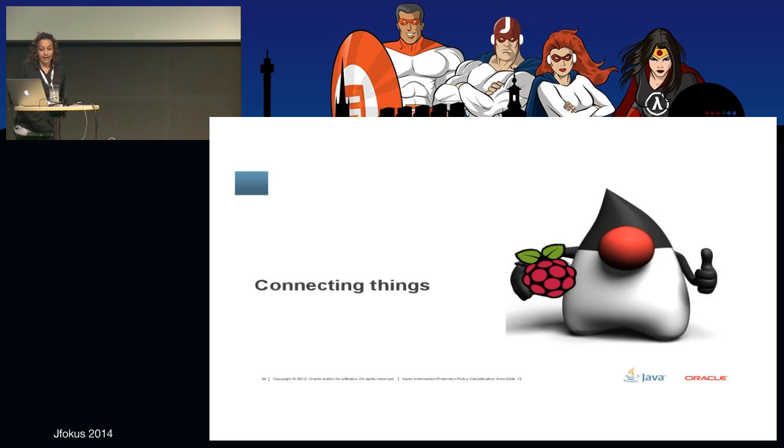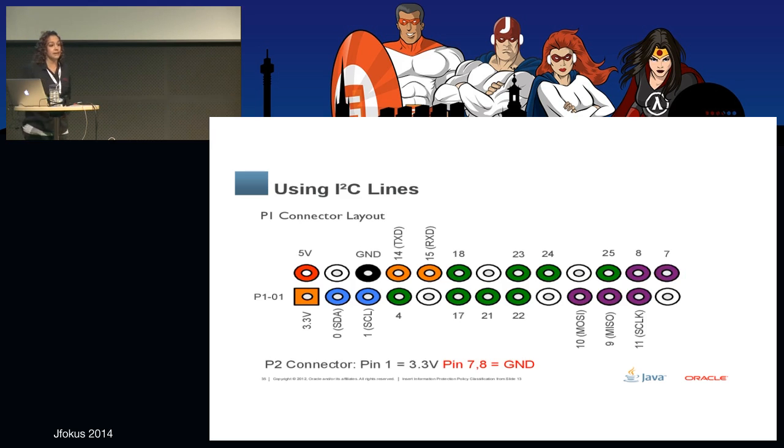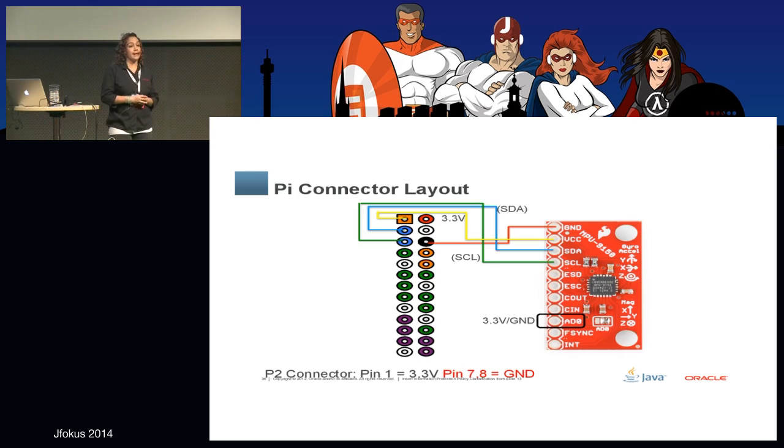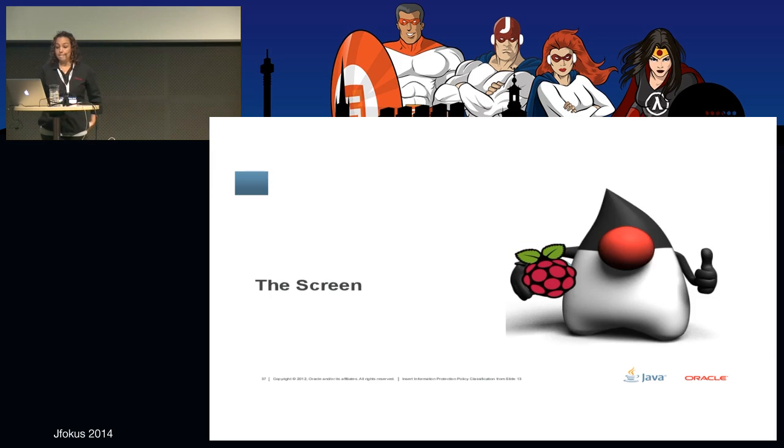How to connect everything. So again, it was very simple, one-to-one connectivity, not requiring any external pull-up resistors. As I say, the Raspberry Pi provides that, so pretty much one-to-one. No rocket science here. Again, remember the AD0 for the least significant bit. So the address of the device will be either 68 or 69, depending on the last bit that you set.